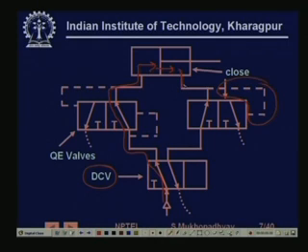When this pressure line increases, this valve is going to shift, as we have shown in the mechanism. Then this is actually connected to this and gets exhausted right there. It does not have to come back to the DCV. So, this tubing is not used for the return path and the air is exhausted right here. So, this is the function of the quick exhaust valve.